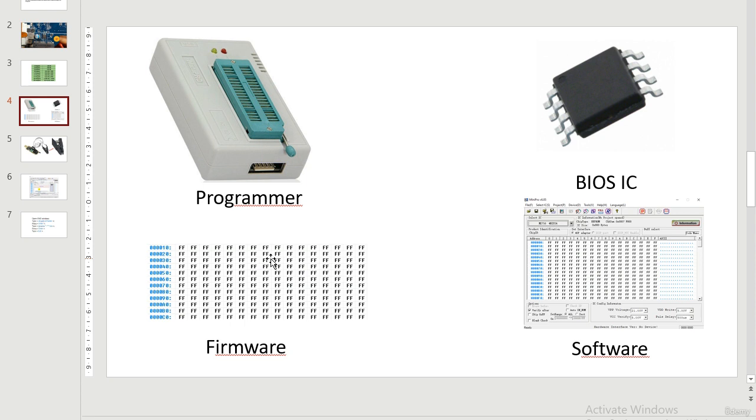But sometimes you cannot find the firmware with a bin extension. So in this case, maybe you should buy the firmware somewhere on a website, or I taught you a trick that you can use to convert an executable file to a binary file, because an executable file always exists.